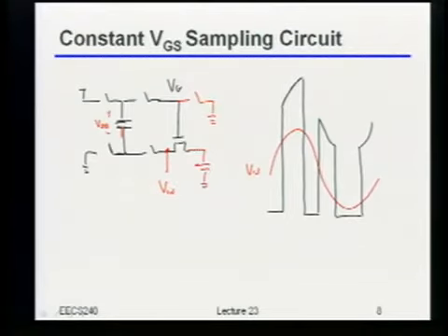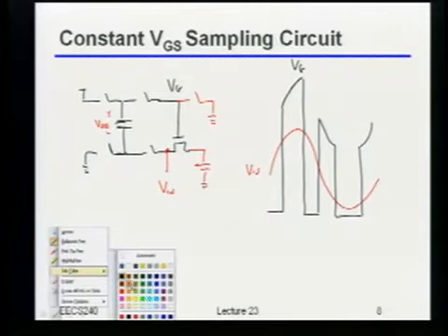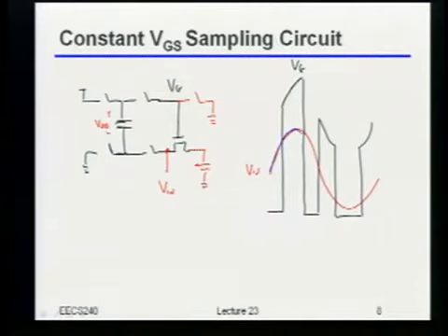Now, based on the waveforms that I drew here, anything you think you're going to have to be a little bit careful about when you actually build this thing? Common mode of the output? Say it again? The common mode of the output, or not the common mode, but the DC level of the output? By the way, this is VG that I drew here. The output, if I've done things right, should just be, I'll do that in blue, V out should be tracking with the input. Because that was the whole point of building this thing. What do I need to be a little bit careful about?